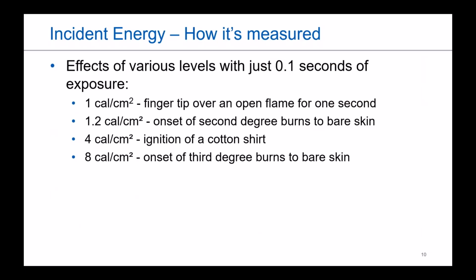And then just to give an idea, you'll typically see incident energy in one of two ways. It's either going to be presented as joules per centimeter squared, which I tend to see more on the engineering side of things, less on the application side of things. When we're talking on the application, it's typically calories per centimeter squared.